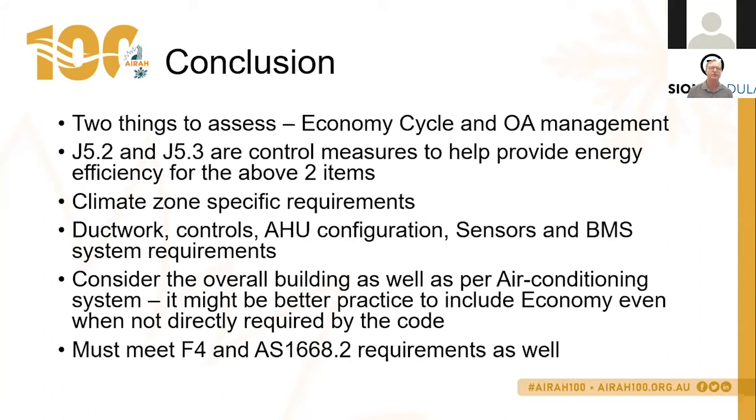That would be a return air sensor per floor, because if one of the floors switches off, which it may need to do under Section J compliance requirements, then you're switching that floor off, and you shouldn't then be using that sensor for that floor's outside air control. Your total outside air rate would then also be adjusted on the requirements. So you'd need to code that into your BMS system, so it would change your set points, etc., on your system.